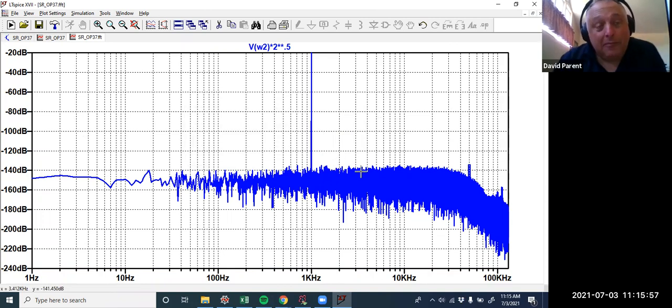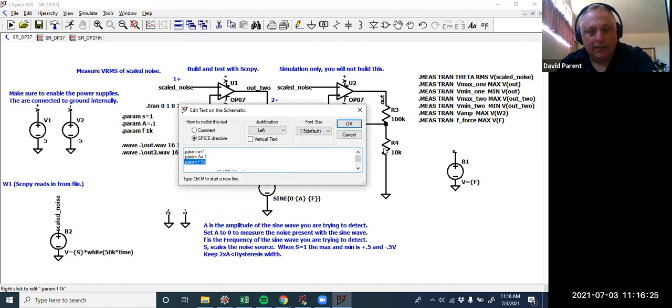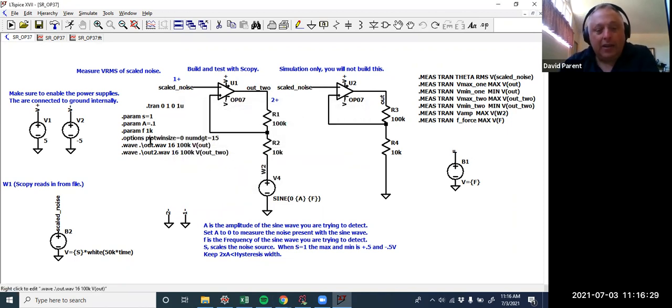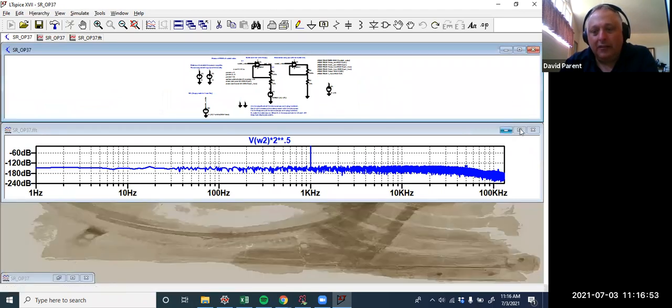And you might say, where did that noise come from? Well, because it's a digital simulation, there are finite time steps and finite precision, even with 64-bit double floating point numbers. In fact, LTspice allows you to control this. LTspice is always trying to make things faster at the expense of accuracy. So this numdgt 15 setting is like in C when you call something a double, a double floating point number. That's what they're trying to say. So that'll just take some time to simulate.